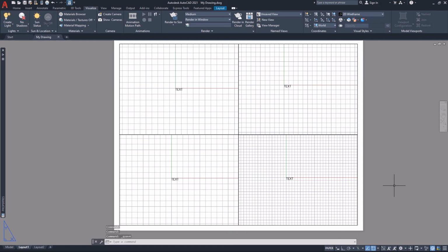The key takeaway here is that graphically, even though each viewport is zoomed in or out to different scale factors, and our virtual grid helps us to visually understand that concept, the annotative text displayed in each viewport remains constant at the assigned 3/32 of an inch text height.